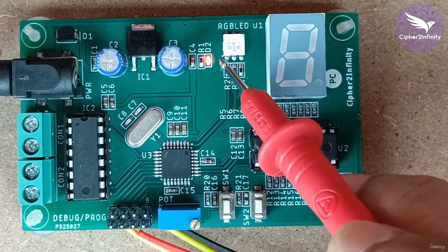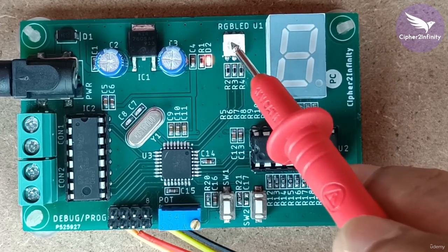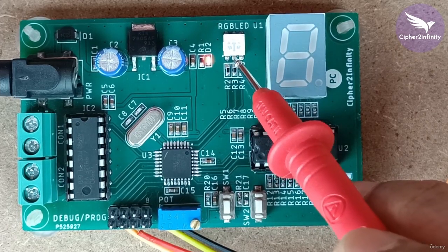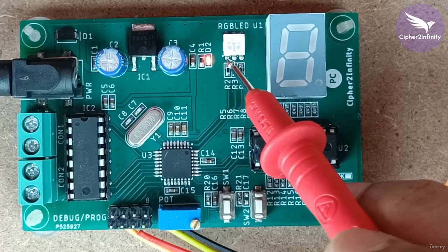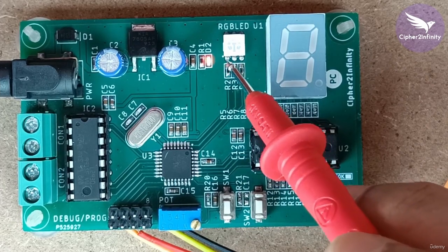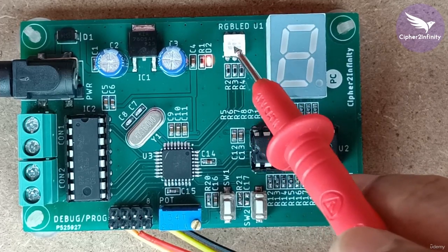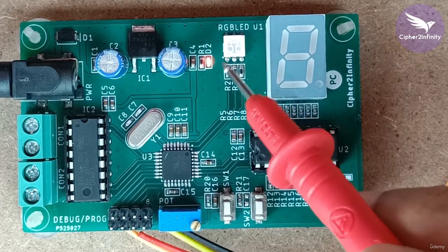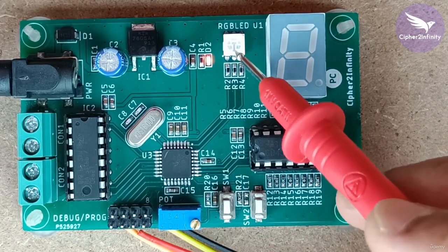So after checking the polarity, now you are sure that the polarity is correct, but still if the RGB LED is not working, then you have to make sure that the soldering of the RGB LED is done properly. Okay, so it might happen that you may find some dry solder. Because of dry solder, there won't be proper contact of the pin of the RGB LED with the pad on the PCB. So you have to do the touch up in that case, and later the RGB LED will work properly. Okay, but still even after that, if the RGB LED is not working, then you have to check the points on the pins of the microcontroller which are actually connected to the RGB LED pins.